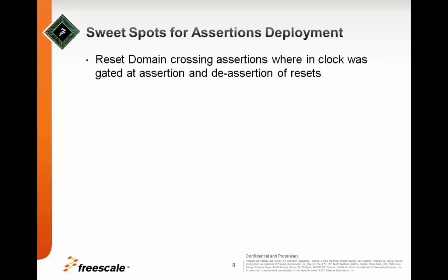With the increase in complexity of the digital design, the reset architecture has also become very complex. Multiple resets are needed in a SoC to reset the various subsystems. The reset domain crossing can lead to issues like metastability, glitches, or other functional failure of the system. In order to avoid these issues, designers have the option to either use reset synchronizers or to match the reset to the clock timings, which is a significant overhead.